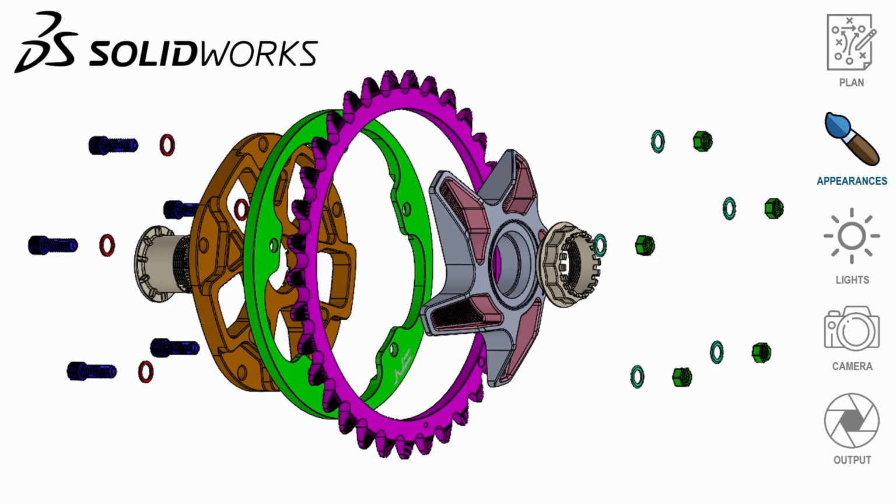The reason why I like doing this in SolidWorks instead of anywhere else is that SolidWorks has some great tools for getting things filtered out nicely. One of the hardest things to get correct in Visualize is actual face applications of appearances, because when Visualize is working with your data, it's not really the CAD data, right? It's just kind of tessellated, so it doesn't have a great reference of what a face is like SolidWorks does. SolidWorks keeps good track of where our faces are.